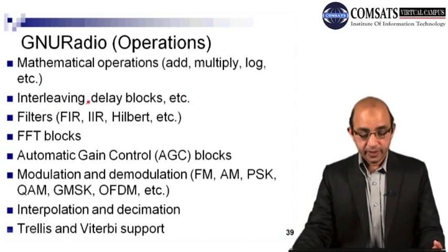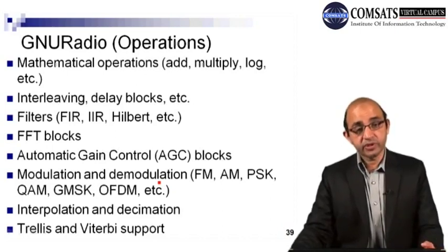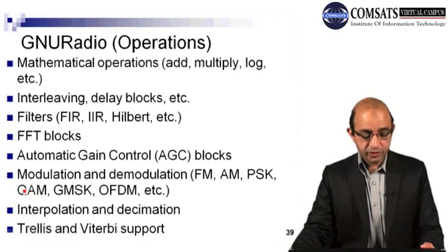Then interleavers, and we have delay blocks, filters, FIR filter, IIR filter, Hilbert filter, and also FFT blocks, automatic gain controllers, and GNU Radio also provides modulation and demodulation schemes. For example, FM frequency modulation, AM amplitude modulation, phase shift keying, QAM quadrature amplitude modulation, and GMSK, that is used for cellular communication, OFDM. And then we have interpolation and decimation.